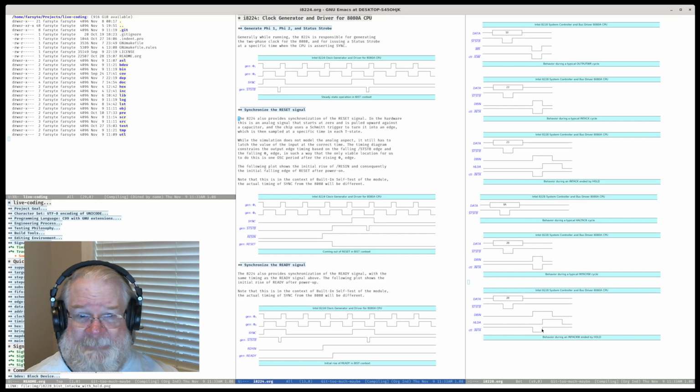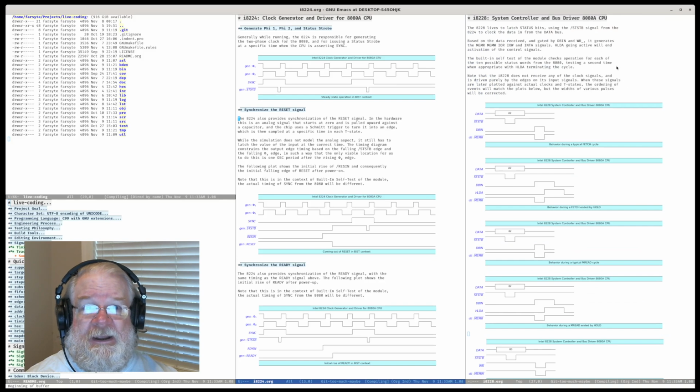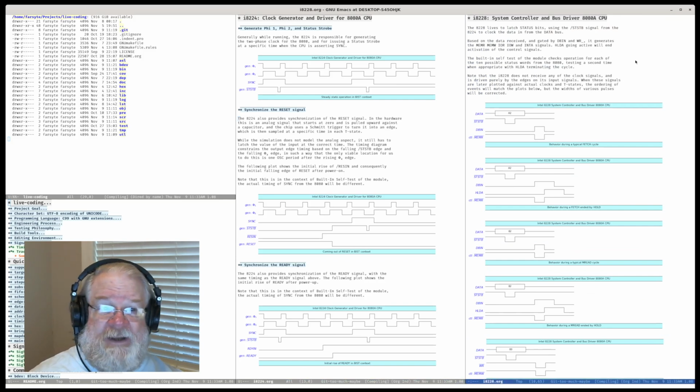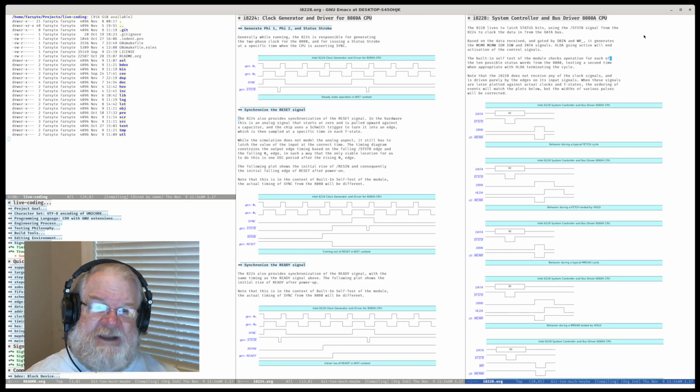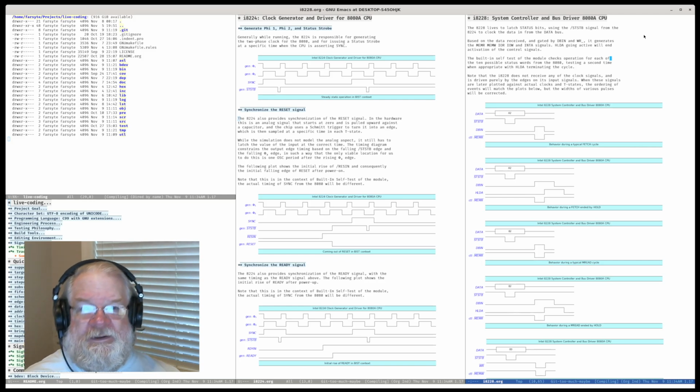And we're not going to do a DMA. So some of the capacities of this chip will not be used during the simulation yet. Maybe someday we will. It would be kind of cool to set up DMA. Currently, every piece of software that I'm using on the 8080, all of the accesses to devices tend to be, wait until we have a byte from a TTY and then read it, or give the disk controller this command and wait for it to finish. So we're going to do all of our IOs with PIOs, so some of this goes away. Anyway, that's the low-level stuff.